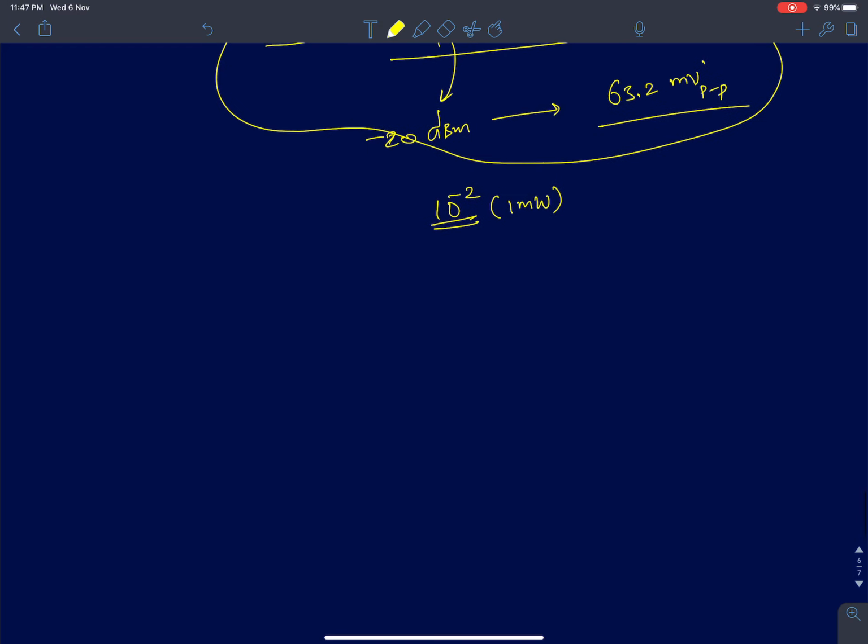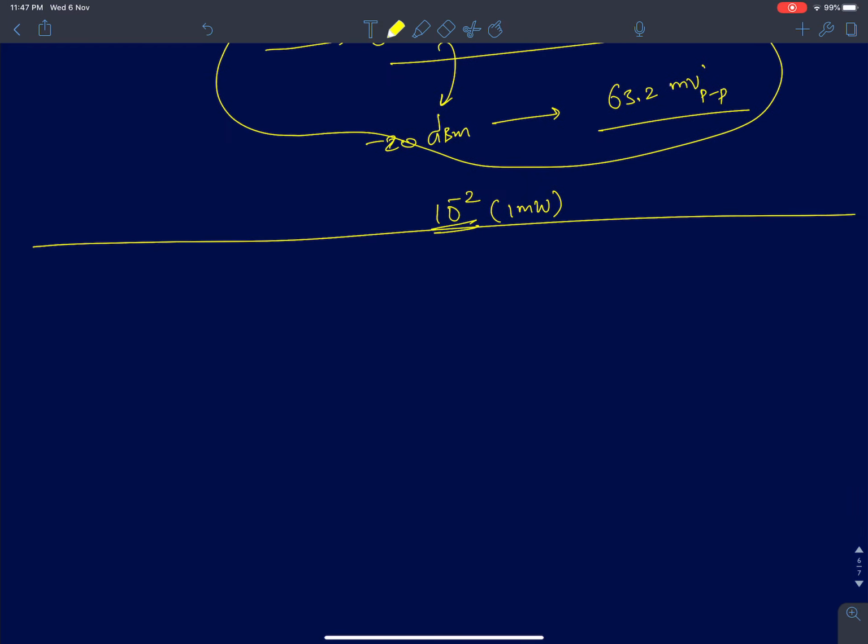So this was the discussion we had about the compression point. And we also said why we care about nonlinearity, especially when you have an interferer. Now I'll talk about the receiver. At the receiver you normally have a low noise amplifier which can be pretty nonlinear. So when you are receiving your signal in the presence of a large interferer, an unwanted signal, we discussed that the gain can be compressed because of the unwanted signal.